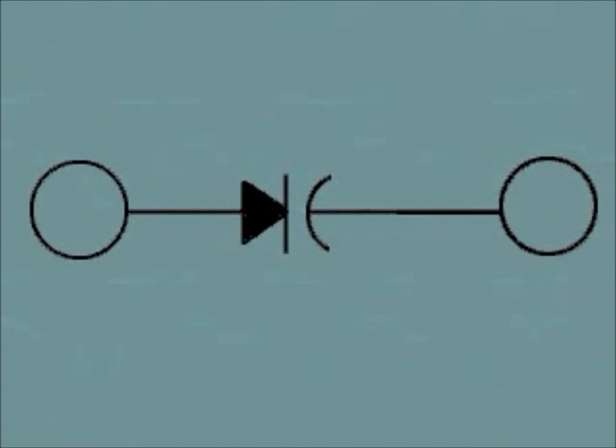The topic for this lesson is varactor and other special diodes. The varactor diode operates in the reverse bias mode and is doped to maximize the capacitance inherent in the depletion region. When a PN junction is reverse biased, the depletion region at the junction has a width that is dependent upon the junction voltage. The depletion region is formed by accumulation of space charge. Because of this space charge and the voltage across the depletion region, it possesses properties similar to capacitance. The junction capacitance is inversely proportional to the width of the depletion region.